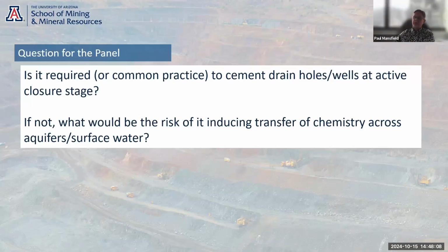I think sometimes there tends to be corners cut with this because you have to remember every time you put in an exploration borehole, you are potentially connecting two sets of aquifers or you're providing a conduit for surface water to get into your system. So you really should be looking at cementing it up. I mean, obviously it depends on the project and depends on the closure plan, etc. But yeah, often people forget about exploration holes until it's too late.